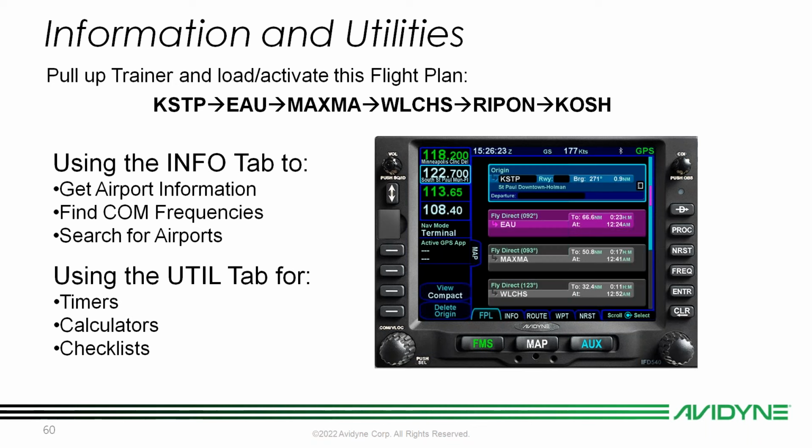Yeah, sure. What's the difference between audio 1 and audio 2 outputs? Which one do all the alerts come through? So audio alerts are going to be an unswitched thing. So the RO alerts, that's going to be a completely different output. Audio 1 and 2, I think I want to say that's the active and standby. Without looking at the diagram, I know we have a separate output for those alerts. So especially our terrain is going to be a TAWS output off of a completely different connector than the other ones.